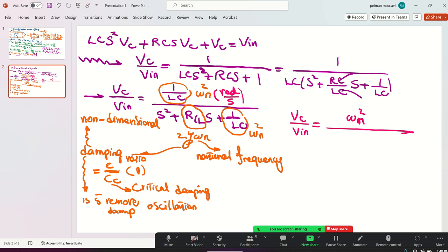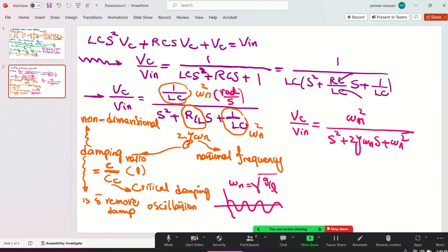Okay, look at the pendulum. Remember in the pendulum problem, the natural frequency of the pendulum was, you have in your notes, square root of G over L, gravity over L. And it was oscillating by itself forever, remember? But when the damper arrives, the damper is gonna vanish that. So it is s square plus 2 zeta omega n s plus omega n square.